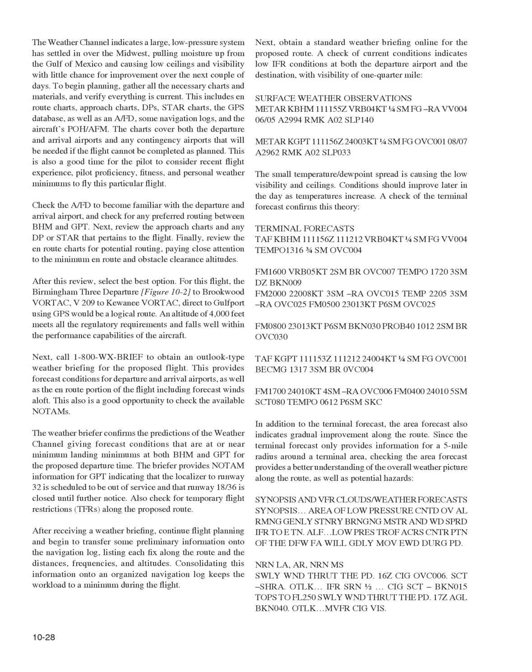After receiving a weather briefing, continue flight planning and begin to transfer some preliminary information onto the navigation log, listing each fix along the route and the distances, frequencies, and altitudes. Consolidating this information onto an organized navigation log keeps the workload to a minimum during the flight. Next, obtain a standard weather briefing online for the proposed route.